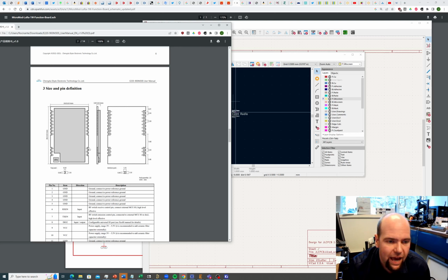So the first thing is these pads. These pads are 0.5 millimeter. There's the top pad and bottom pad. The bottom pads extend a little more copper into the board. If the bottom pad is 1.25 millimeters, is 1.5 millimeters high, and it hits the castellation halfway, I'm going to make pads that are centered on the edge of the board that are actually 2.5 millimeters wide. So I'm going to go with a wider one.